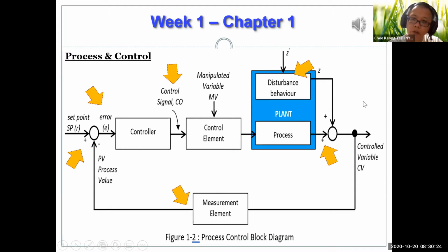In the aircon room example, my desired temperature is, let's say, 25 degrees, but right now it's 30 degrees. So you look at the environment, it reads 30 degrees, and you subtract 30 minus 25, which is 5 degrees higher. You tell the controller there's a 5 degree difference. The controller will pump the fan and decrease the temperature, and you go on looping until it reaches the set point.